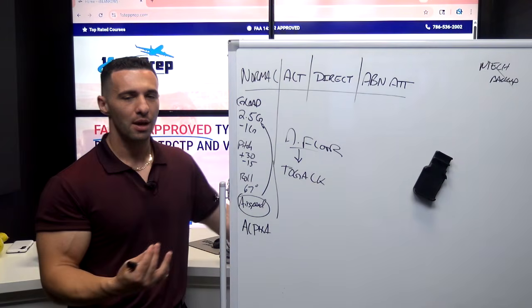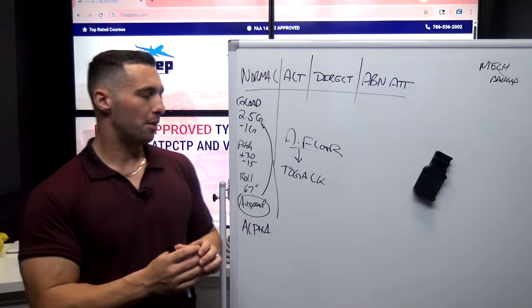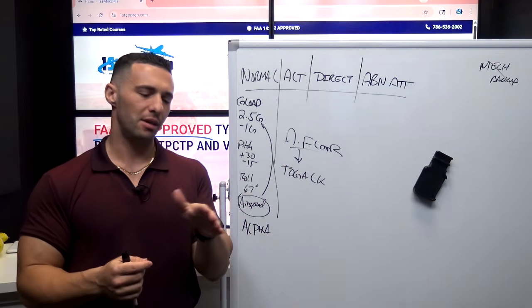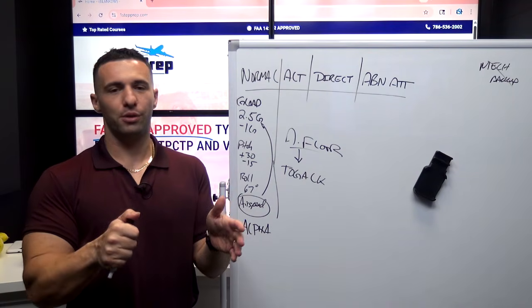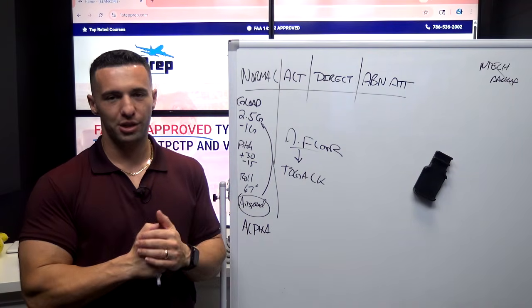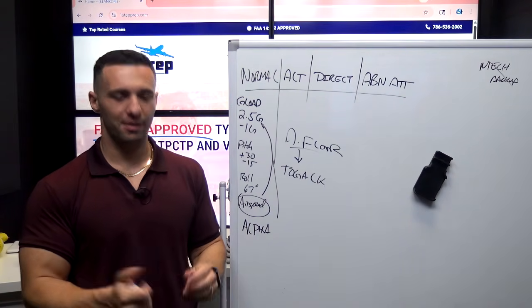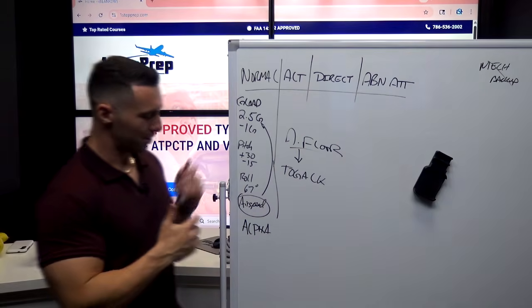In the simulator, I validate and demonstrate the predictive nature of it by usually putting you in maybe a flaps 2 configuration, 180 knots, and then just disconnecting everything, hand flying, putting in a 30-degree bank and pulling a considerable amount of G's on the side stick. Before you know it, we're not necessarily too close to VLS at that point, but still, nonetheless, we get alpha floor to activate, and that's a good demonstration of that.